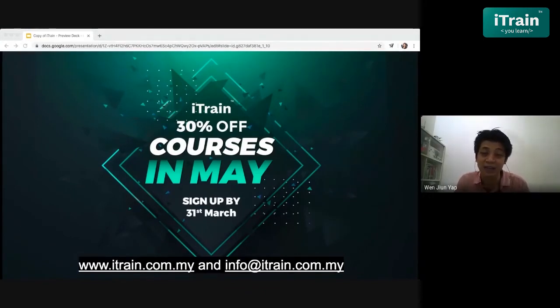For the IoT project here, of course, you can see it from the diagram before. There should be something that you are connecting to your Raspberry Pi, or the Raspberry Pi itself is a sensor or the actuator. A Raspberry Pi has very few sensors inside, so you probably need to install something called a HAT, an additional module that you can plug into the pins there. Then it can sense something.